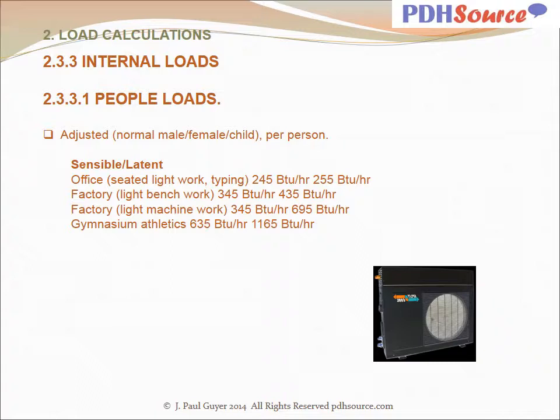In addition to those loads, you also have internal loads that you need to take into account when doing the cooling load calculation. You ignore these internal loads when doing the heating load calculation because essentially they amount to a safety factor in the heating season. So you just accept these safety factors, and they help to heat your building in the winter, but you have to compensate for them in the summer when you're cooling the building.